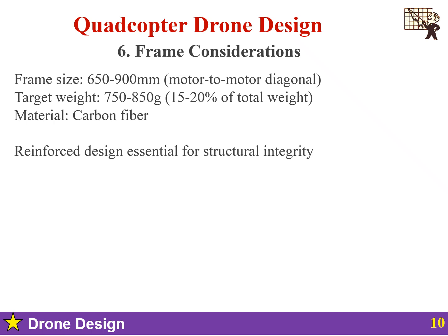Next is the landing gear. At 5 kg, landing forces are substantial. Retractable gear for unobstructed 360-degree camera views. Shock absorption for 1 to 2 meter per second landing velocities. Sufficient ground clearance for gimbal and payload.